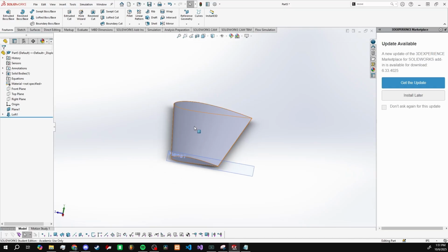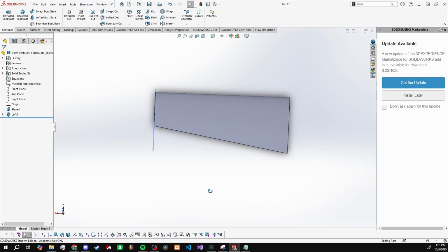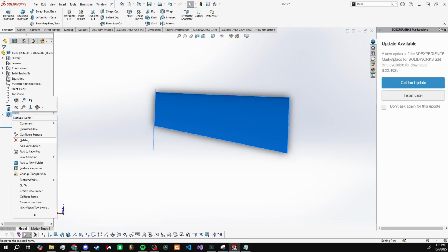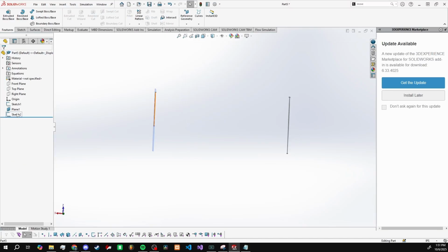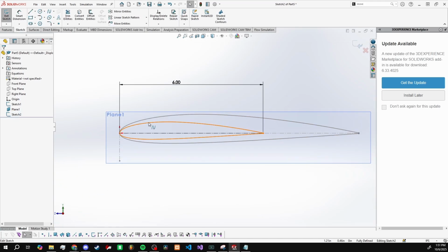So pretty simple in that sense, but let's say you wanted a mid tapered wing. So the front is going to be tapered, or technically it's going to be swept, as well as the rear will be swept. So if we delete this loft and we go into sketch 2, which is going to be our wingtip, you can see that the sketch is fully defined.